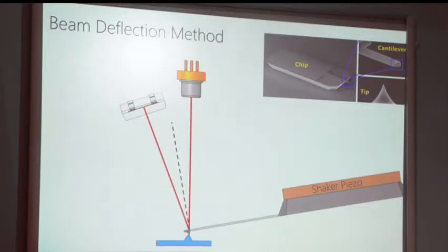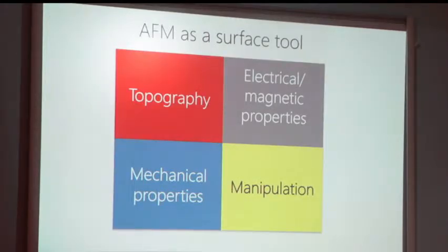So when you get this volt and you know the piezoelectric coefficient of the scanner or the piezo material, then you can calculate how many nanometers it is. But the good thing is that you are not supposed to calculate all these things by yourself. The software and the controller, all combined together, will provide you the data in nanometers. So you are not supposed to do anything, provided you have calibrated your AFM completely. Calibration of the AFM is very, very important in AFM measurement.